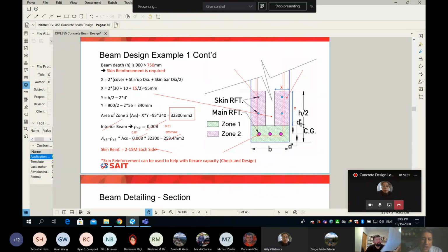So Jelly is saying, if you're designing a beam and you keep rho, which is at the very bottom, this cannot be more than rho balanced. So if we are very close to rho balanced, and we come back and add a couple of bars each side, and I know they are little and their lever arm is not that much, but if you want to estimate it right, you have to find the centroid. So this may turn you into a balanced failure. I completely agree, and that's why a good designer will not even use this.